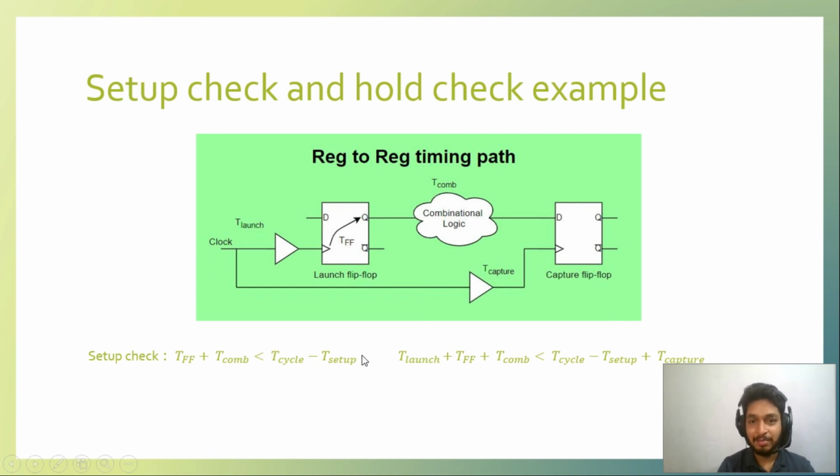So for setup, it is a very good help, because this increases the time for the data to arrive at this point, because the clock itself is coming late. So the data also can come a little late. That is good for setup, but it is bad for hold. These kinds of things are always a trade-off between setup and hold.